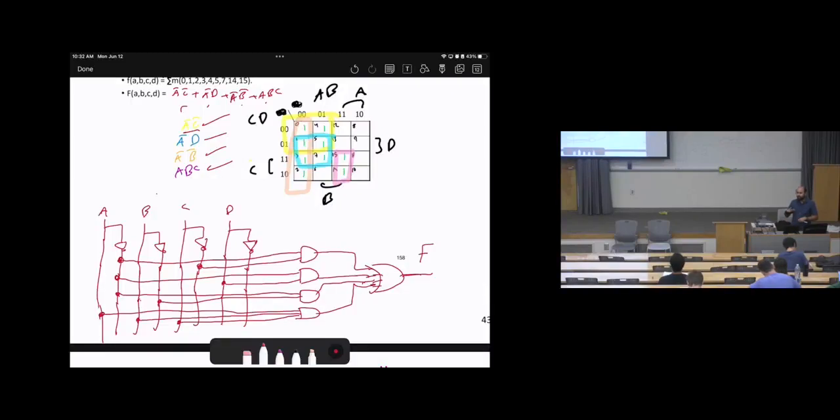Then after that, the next step, we manipulate the function f, then convert this function f from a complicated one to a simplified one using either Karnaugh maps, or canonical forms, or Boolean algebra, but we prefer to standardize our answers, so we need to use Karnaugh maps by converting the function to canonical form, then make the simplification to get the simplest form.